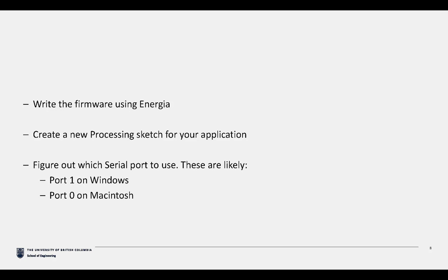Once you finish this, run your code and you should see Hello World being printed out in the terminal. If you don't, you can use the serial monitor in Energia to see if the Hello World message is being printed properly as a debug step. Make sure this part works properly before moving on, as we cannot continue with the lab without making sure this works first. Now that we know we can communicate with the Launchpad, we're going to collect and graph incoming data.